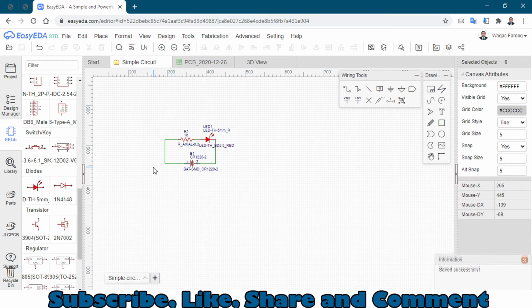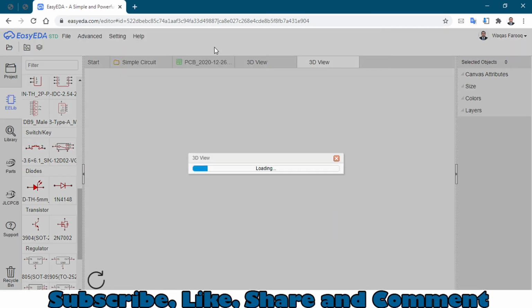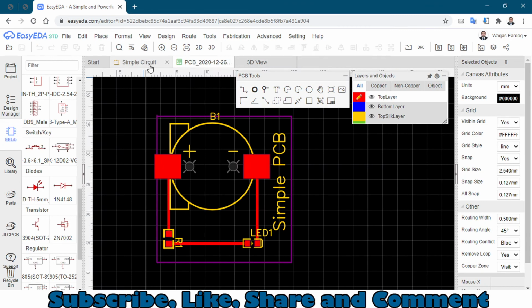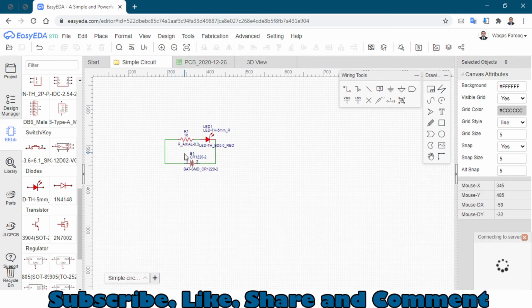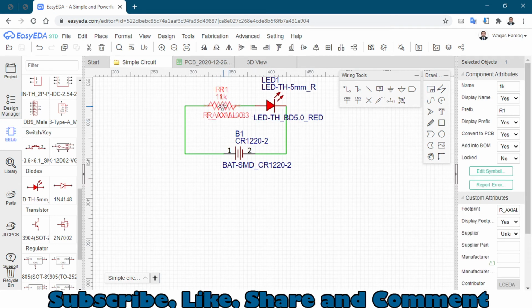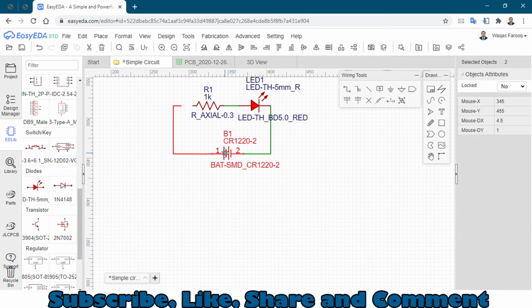Just press Control S to save, go to the PCB layout and click on Save right here, and now click on this 3D view. As you can see, this is an axial resistor, an LED, and a battery.